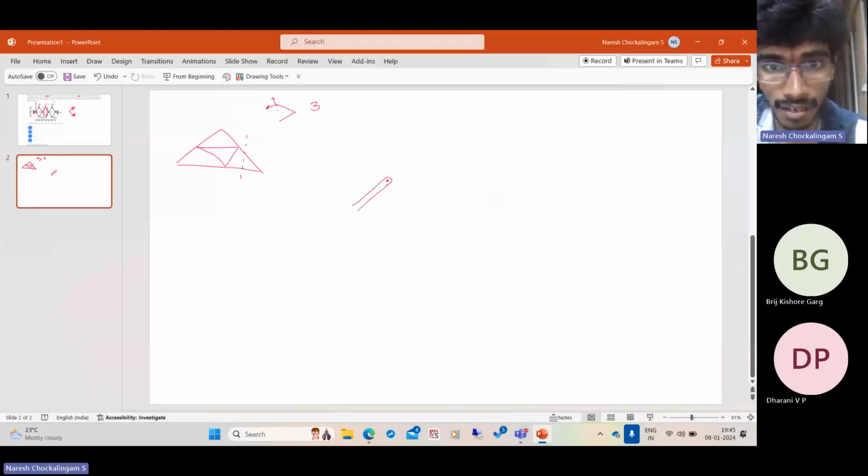you have a pin and you have another member connected here. And this is a continuous member, so this extends here. So it is something like a scissor. And a scissor bends when you try to cut something very hard, right? So it is not an axial force member. It is not a truss member. So you have something like this.